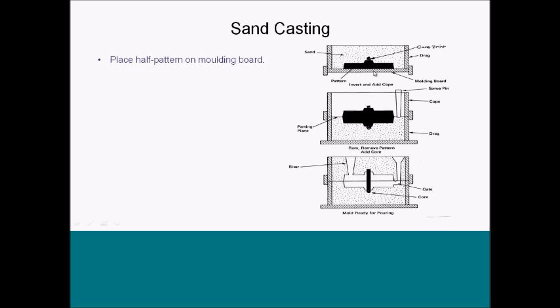So there's actually two pieces, and that's going to enable us to build the sand around our pattern so that we can then pour the metal in and form the shape, and also have a little bit of a runoff here for excess metal to go into, to make sure that our part is completely full and we don't get any air trapped in there.